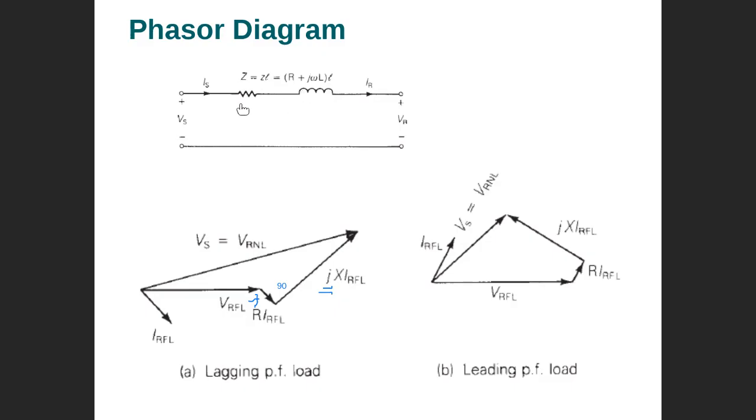But as an engineer, you need common sense. You are familiar now that X is higher than R. So if you read the data and see otherwise, you can tell the data is wrong and has some problems. Maybe the data entry person entered a wrong number, maybe writing 0.1 per unit for R and 0.01 for X. It cannot be like this, so you can determine there is something wrong in the data. This is what engineers do when they work on planning or calculation.